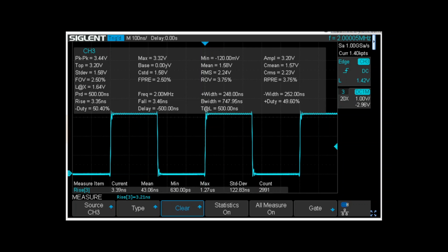The rise times are being measured, and curiously, they're actually a little bit lower than what the other probe got. And there's not much difference in the rise time between 4 milliamps of drive strength and 16. I don't think I trust this measurement as much as the last one, though, just because of the load on the circuit. It's a variable that's hard to account for. The waveforms definitely look good though, so maybe Horowitz and Hill are right about it being a good way to capture waveforms for a book.